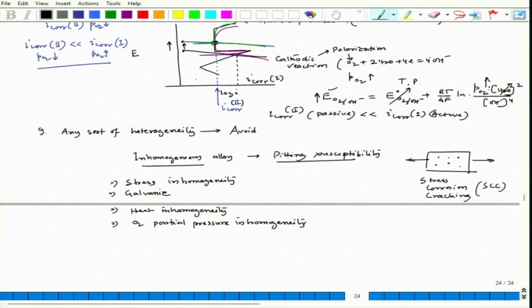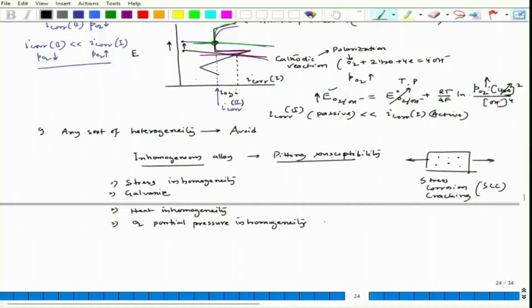At times what happens, let us see some section, if that section gets a less amount of oxygen, you are going to create a high degree of concentration cell. So, the low oxygen place can have higher anodic tendency, and this is related to concentration cell. For example, if some places we are seeing crevice, if there is accessibility of sending air, if we send air, actually crevice corrosion can be prevented to a great extent. What we are doing, we are actually avoiding depletion or replenishing oxygen there.